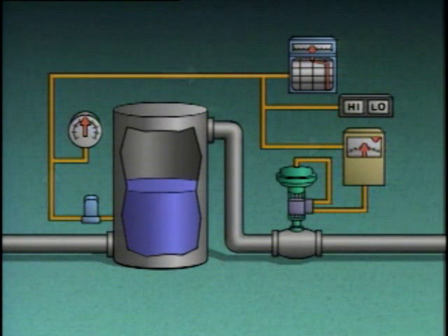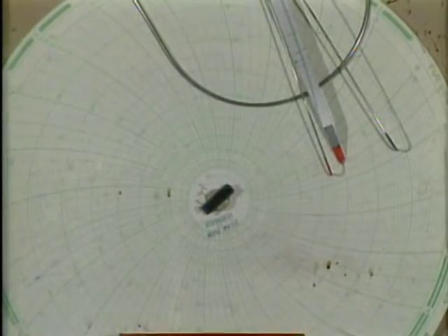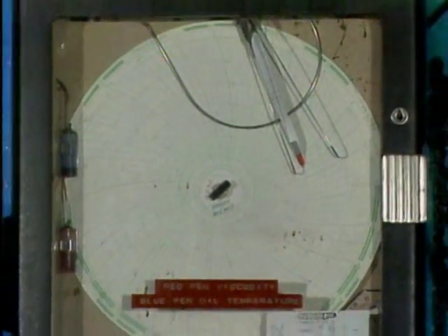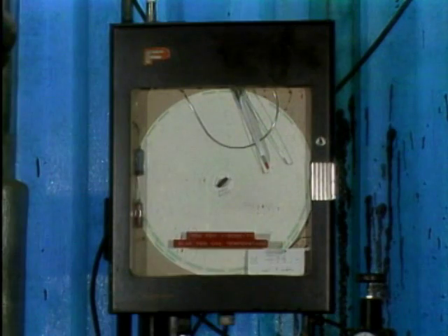It operates by receiving a pneumatic signal from the transmitter, comparing that signal to set point, and sending a pneumatic signal to the final control element if necessary. So it can be referred to as a pneumatically operated level controller. Some controllers have a chart to record process variable values over a period of time. This controller could be called a recording controller.